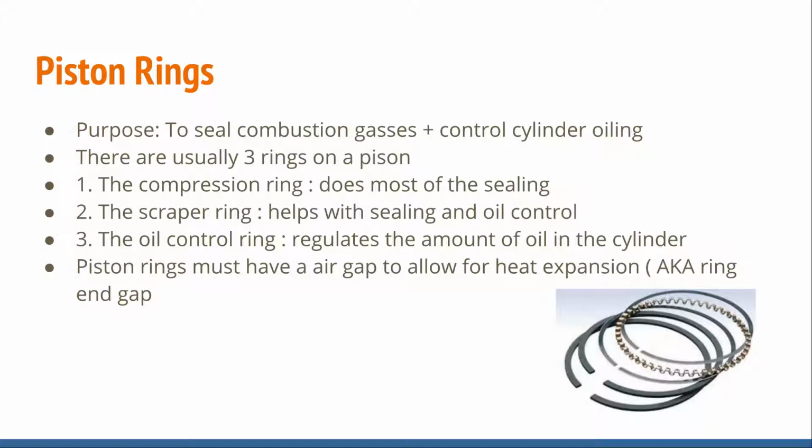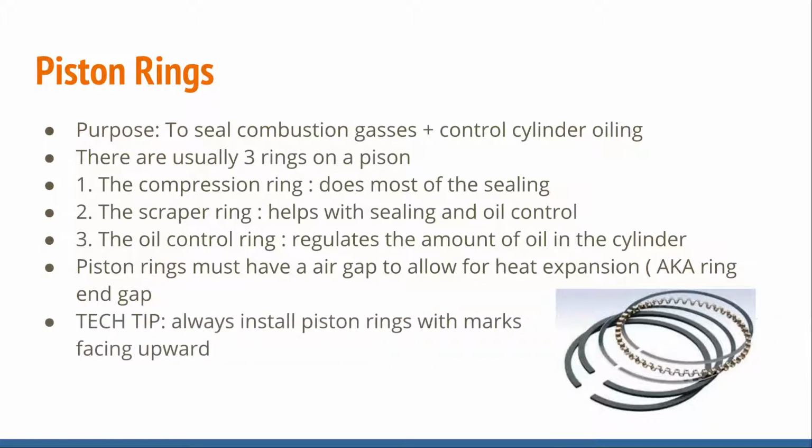There's always going to be a small gap there to give adequate room for heat expansion. If those rings touch, bad things are going to happen. The rings are going to bind and it's going to tear stuff up.